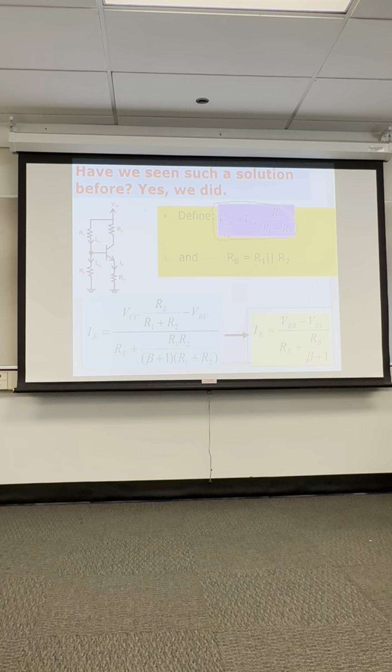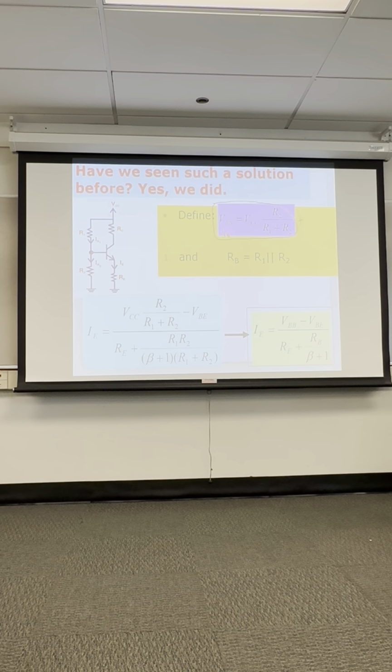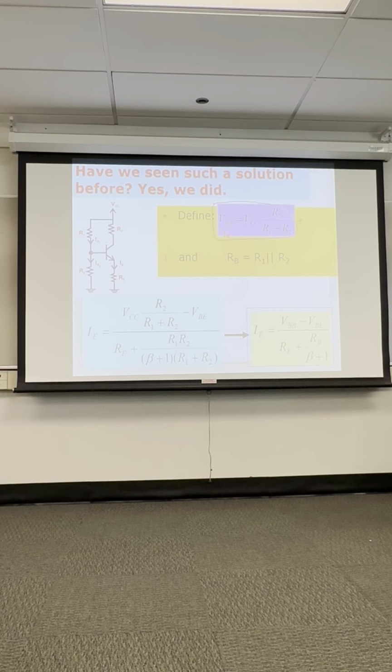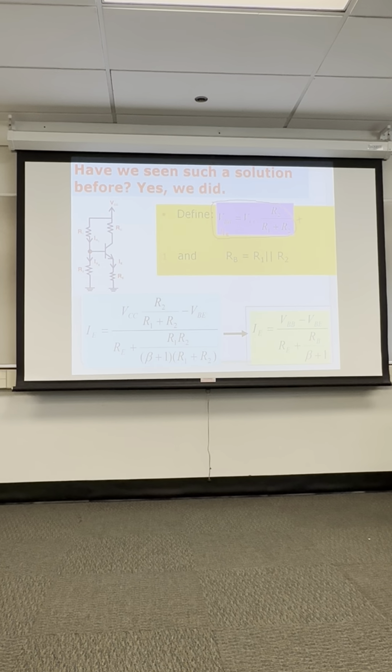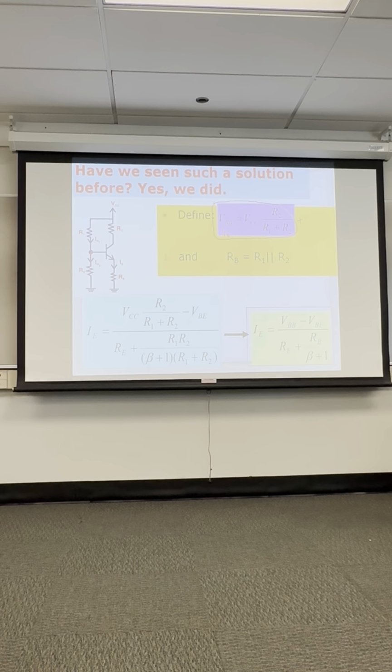And it's showing a current law with only two components of it. There's actually another component over here. What other component should be in this equation to be accurate? Base current. This equation is assuming the base current is 0. Which is probably okay to start an analysis, assuming the base current is 0. And as I said, this becomes a voltage divider at this point.